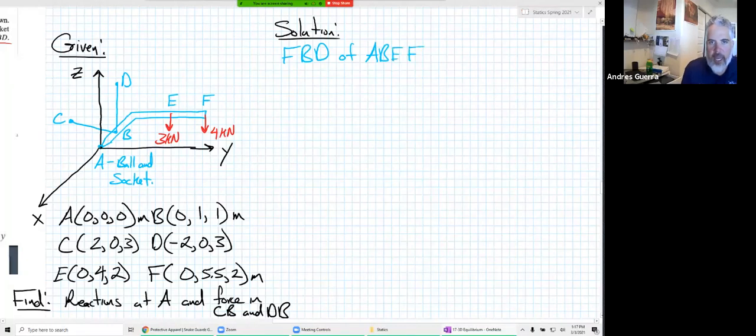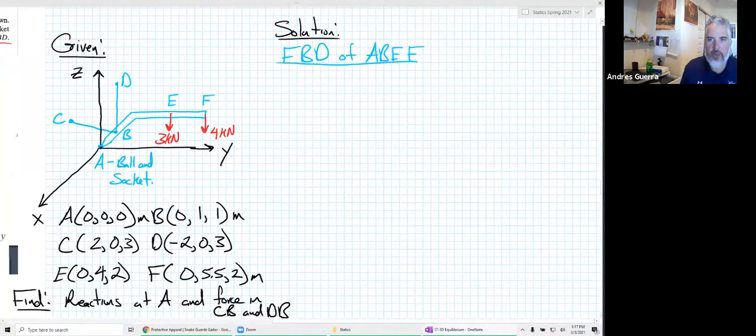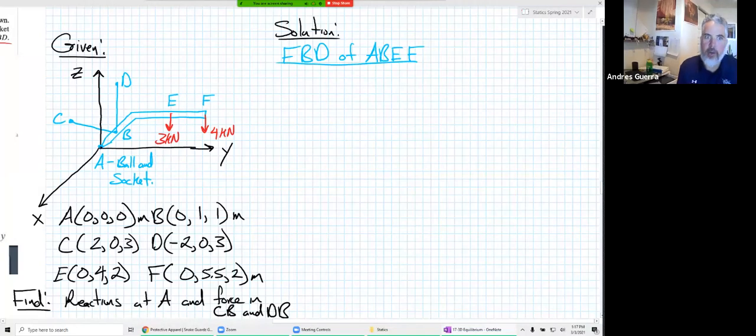to F. And if we really wanted to go through our process and consider B to C and B to D as rigid objects and whether or not we should do an FBD of those, they don't have any known values. And so we really don't need to look at those anyways. And actually, we don't usually draw FBDs of two force members because they don't have any known values on them. So yeah, let's start with our FBD.